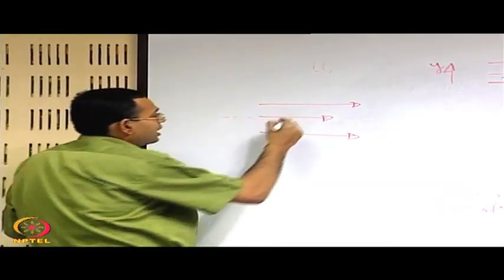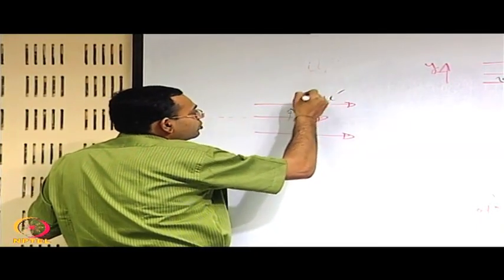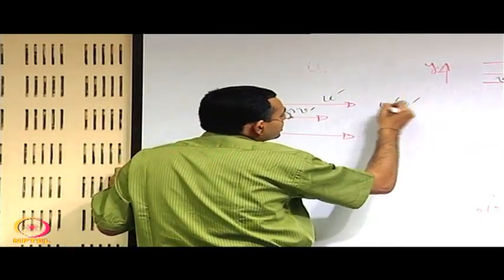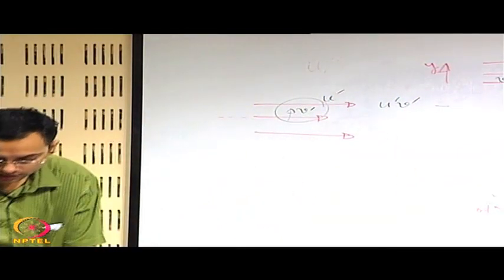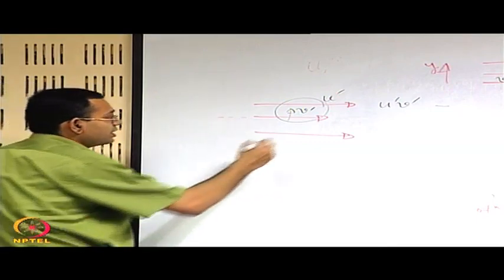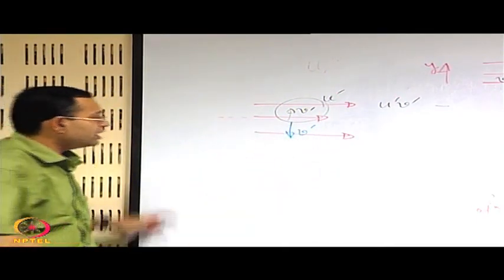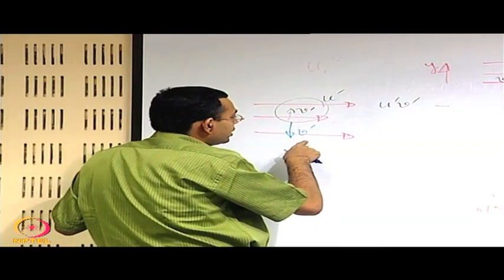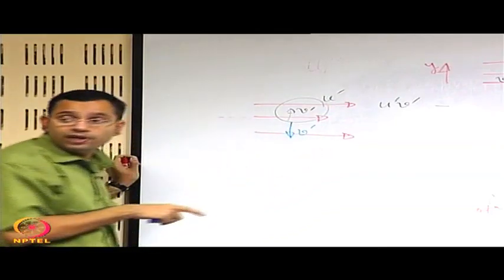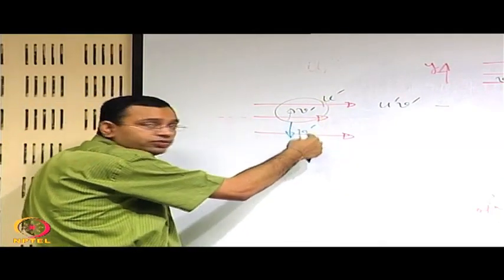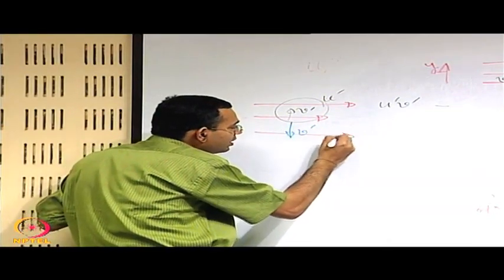Now in this case, if you have a positive v prime, it will associate it with a negative u prime. So u prime v prime is negative for this interaction. Let us consider a similar interaction when it comes to a negative v prime and it interacts with the lower layer. So here a negative v prime is associated with what? A negative v prime is associated with a negative u prime, because it comes from a slower moving layer, so it tries to slow it down. So negative v prime and you have a negative u prime.